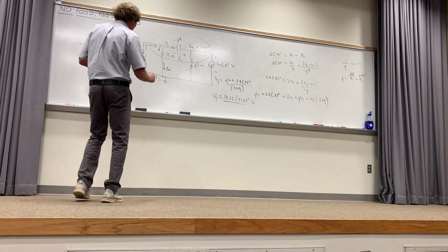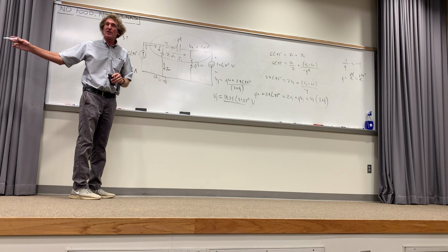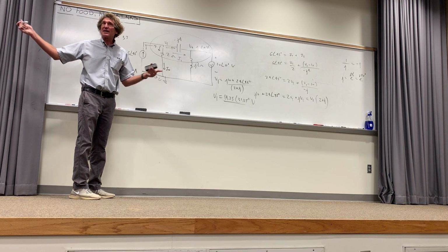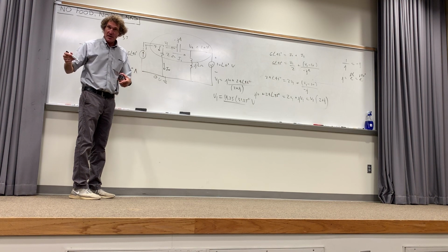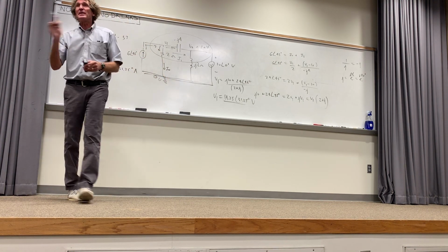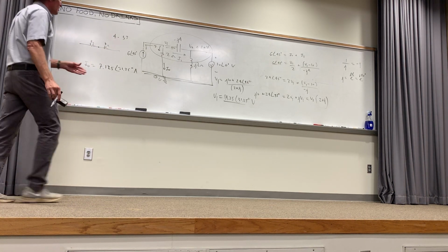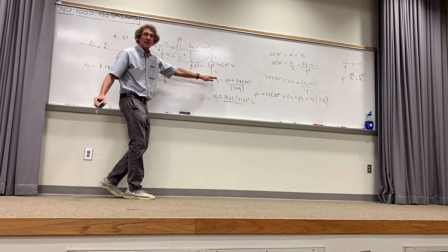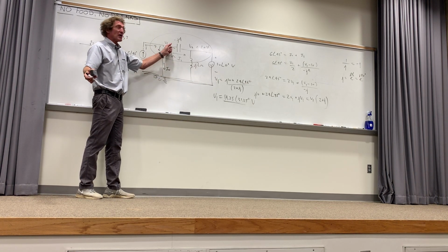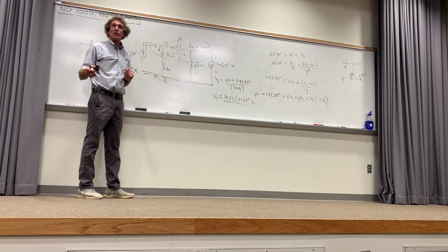Yeah, here's what it comes down to. Normally, in any circuit that you can imagine, you're going to have some point in that circuit where it has the most amount of connections, right? That's where you put the 0 ground, unless there's a tremendously good reason not to put it there, right? So if you take a look at this, you all see how all these things are at the same point. Just put 0 volts. Because if you want to solve for that, you make a ground here, it's stupid. You're going to have crazy equations. Just leave that as 0.